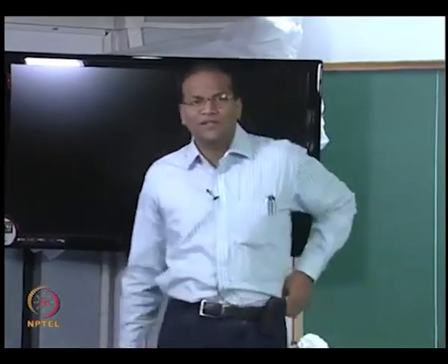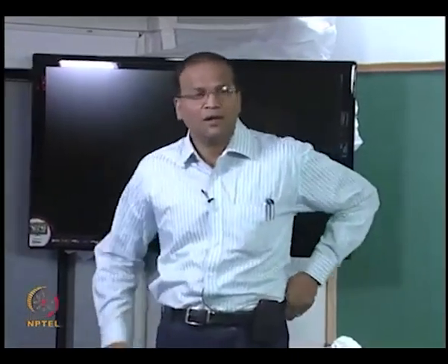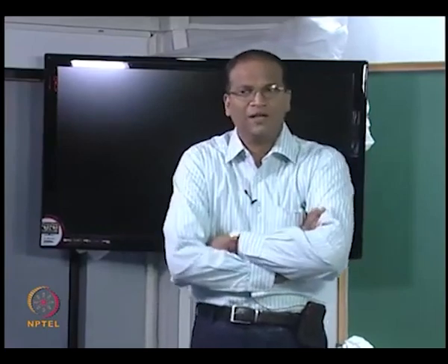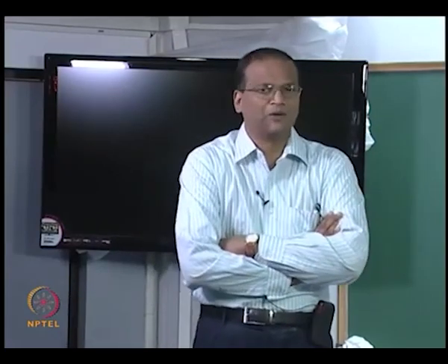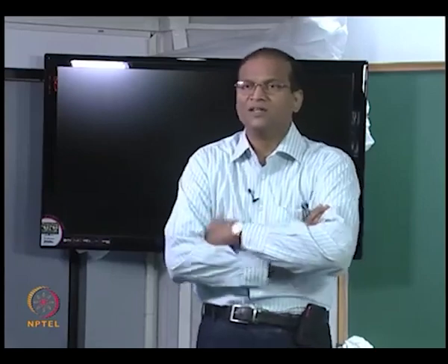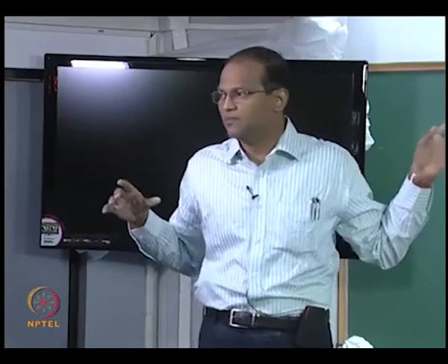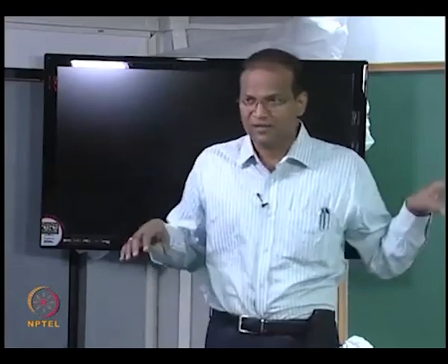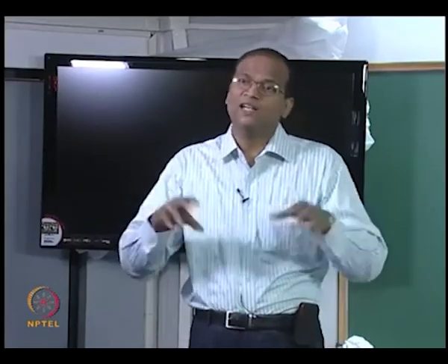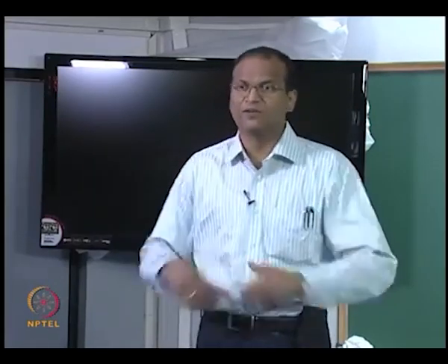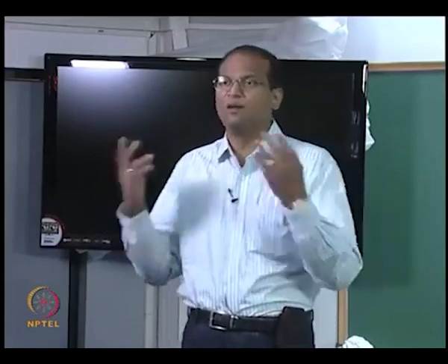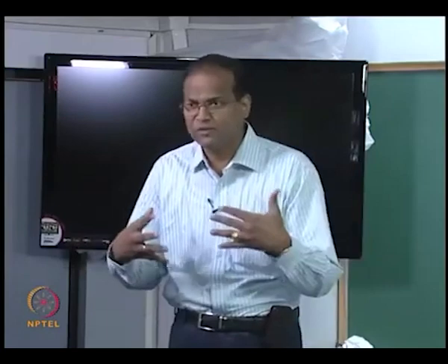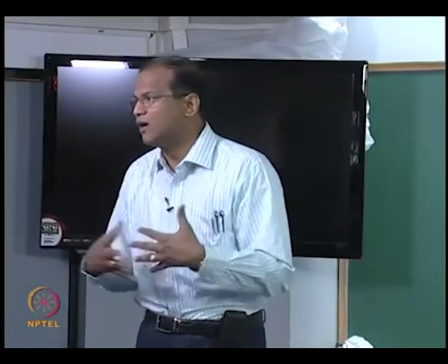So, this is how you solve problems involving epsilon. Now, there are other properties like reflection, transmission, absorption and all that. Each of these may have a variation with respect to lambda. You need to characterize all this, and then your energy equation may not be so simple. There may be combined conduction and convection, then you have to handle this. Now, the energy equation may be such that you have to solve the Navier-Stokes equation, or the Laplace equation, Poisson equation, then you have to add radiation to it, then it becomes a multi-mode or combined heat transfer problem.